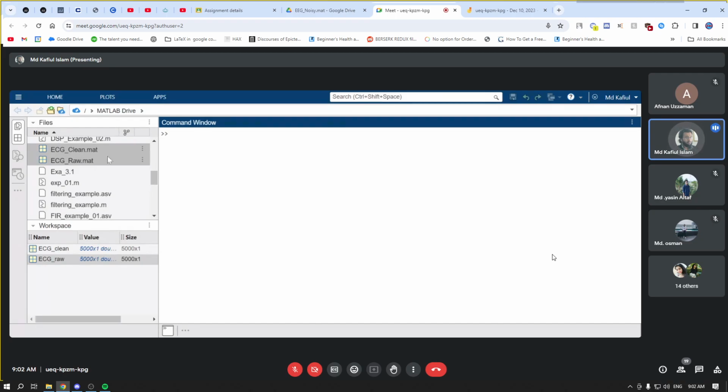So I do not know at the moment what the sampling rate is, but I can still hopefully find out. So we can use pwelch, which is a built-in function. pwelch is actually the power spectral density of any signal, through the Welch method. So Welch is the method, and P is for power spectral density, or power through Welch. Power spectral density means power in the spectral domain, in the frequency domain.